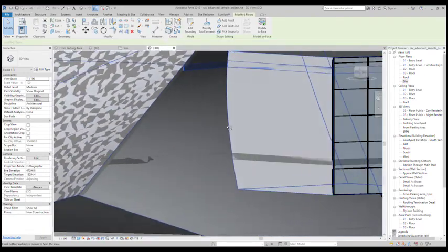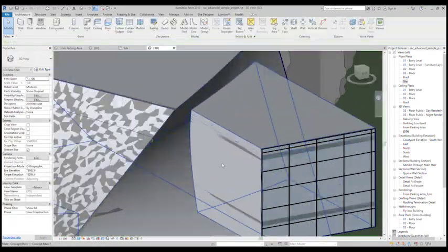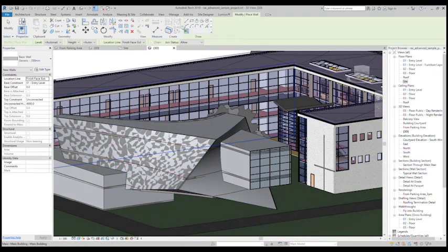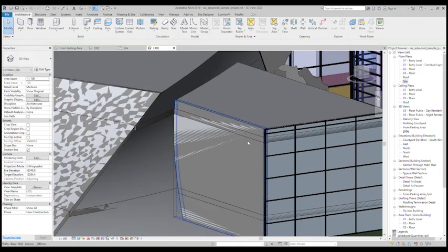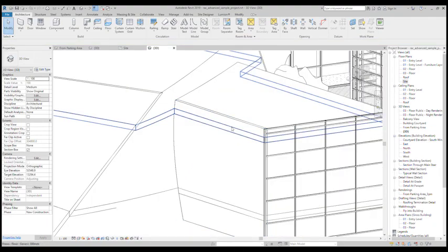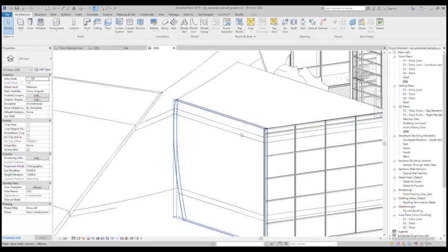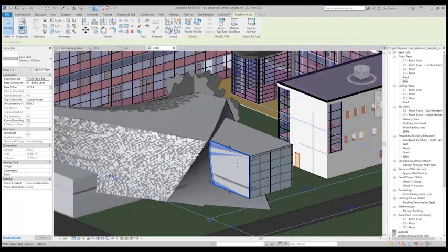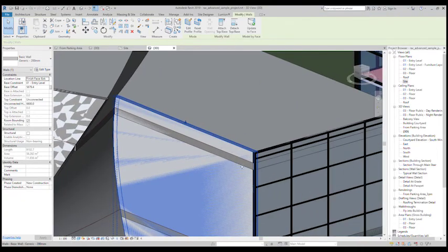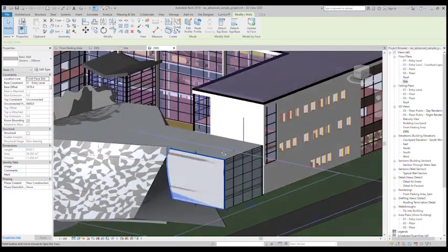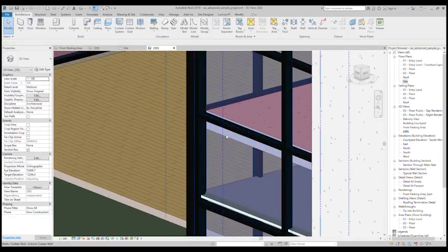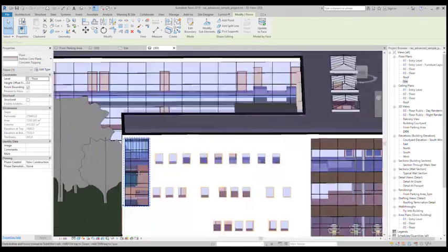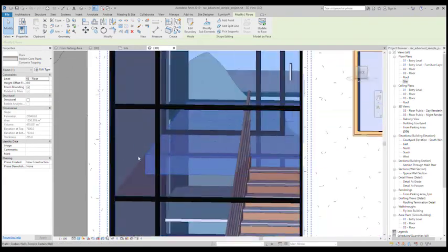These floors are all going to the edge of the masses. That is an irritating thing, because once we start adding more walls to this model, you will always see these solid lines of the floors running through the model, and I really hate seeing that. In reality, walls sit on the outside of floors. Floors terminate on the inside of walls. Like you would see here, that floor in this building is running on the inside of the wall. Can you guys see? It's not going to the outside.